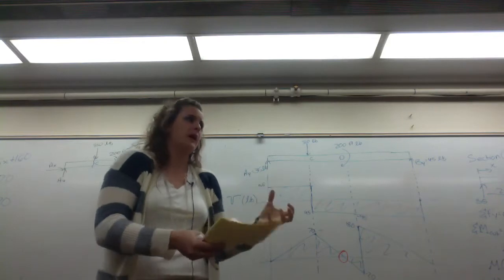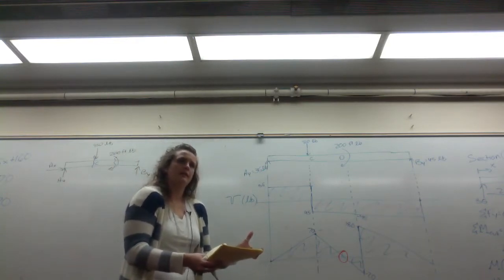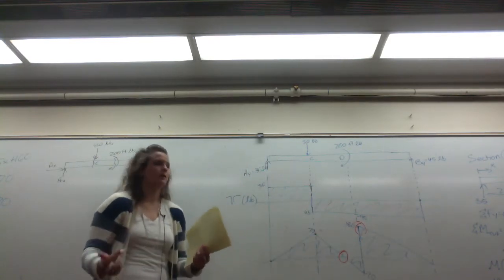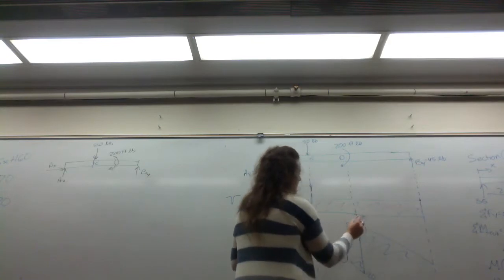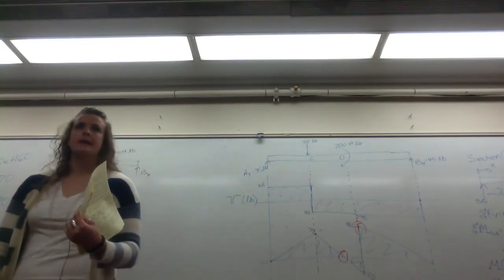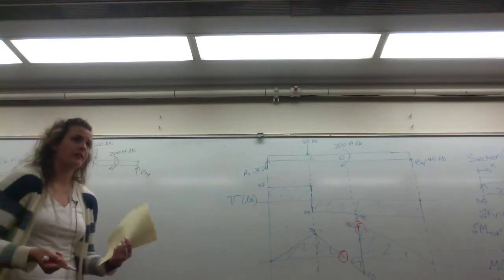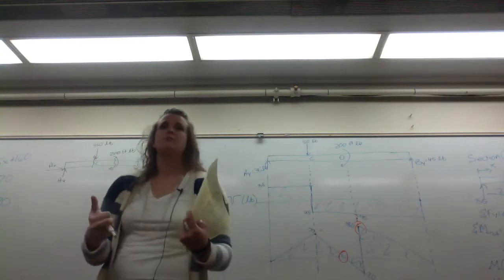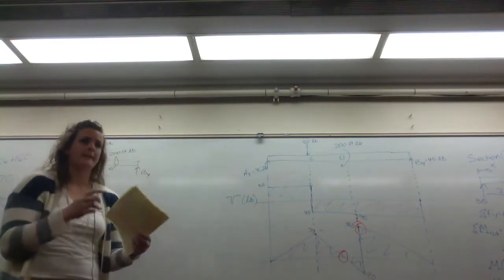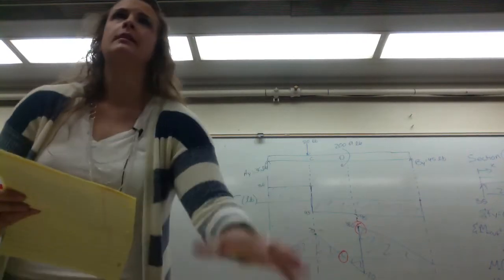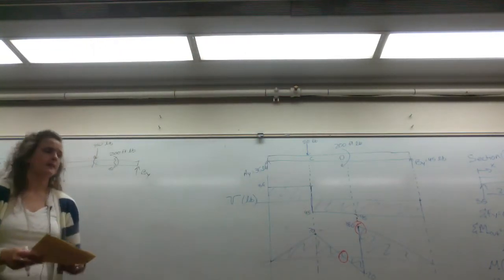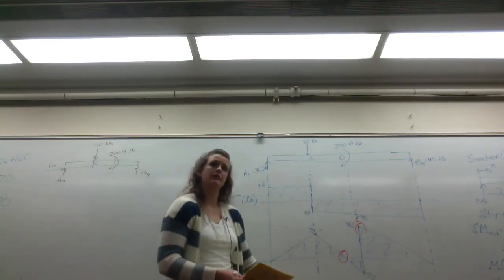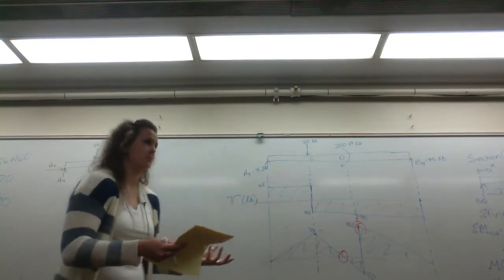But what causes things to break also? High moment, right? This torque. This maximum torque coincidentally coincides with your maximum shear. So your chances of failure, this is getting into reliability, your chances of failure are largest where your maximum torque and your maximum shear force are. Okay? So just a couple applicable points. Right? But this stuff isn't just math, right? You go into any structural analysis and use this stuff. You can use these to understand what's actually going on in the beam.